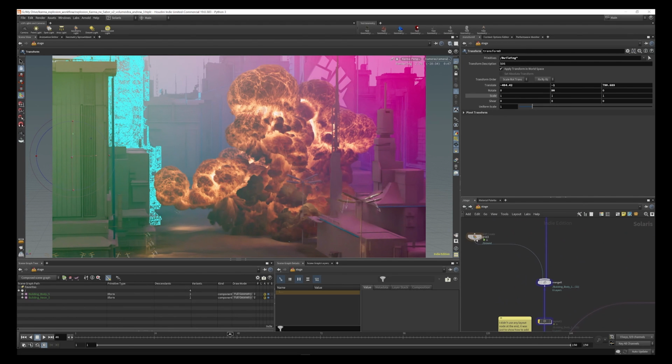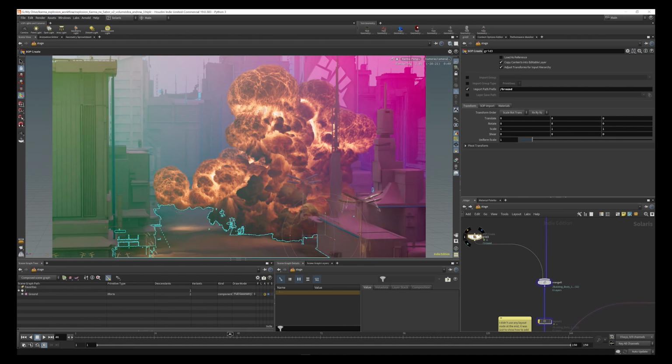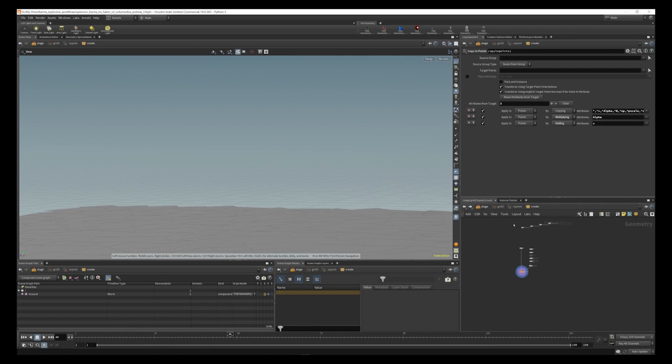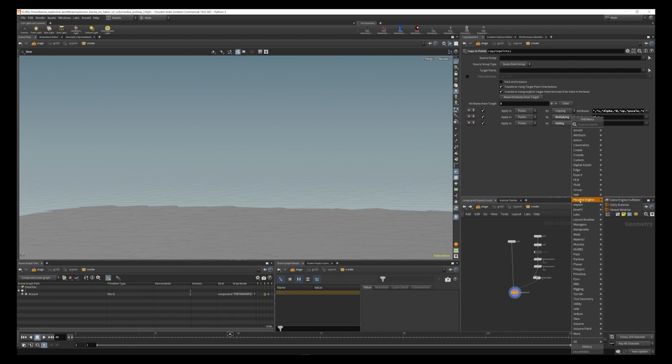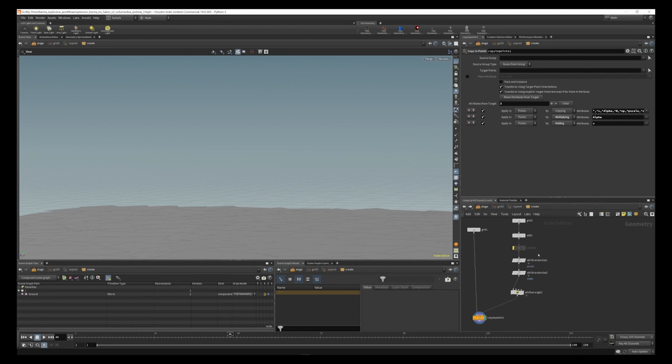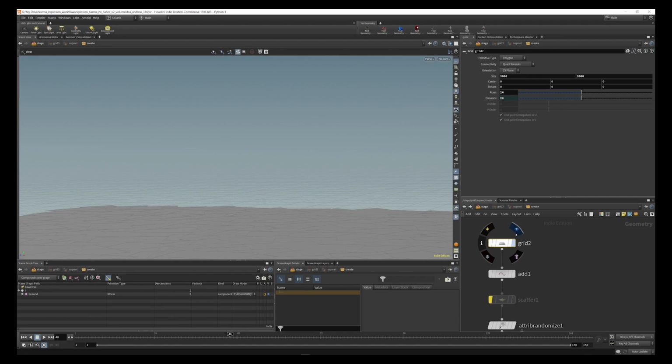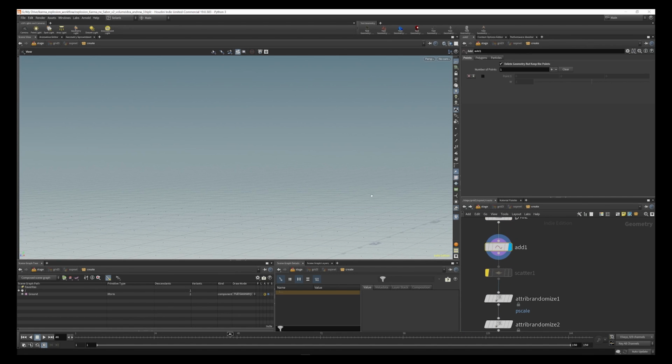From here, we've got a SOP geometry. So this time, we're not importing from Stage. We're putting down a SOP create. And what this node does is this actually allows us to jump into essentially SOPs within Stage. And here we have access to all the nodes that we do in SOPs. So, you know, in this case, we've got a grid here. We're putting down an add node to create some points.